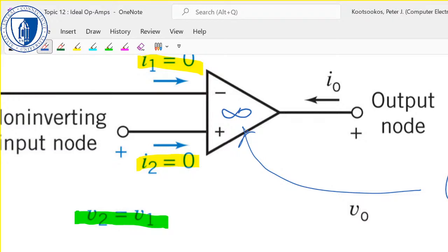As you change the frequency, at DC it's that level, at zero frequency. At a gigahertz, it's nowhere near that. It's maybe 1, maybe 2. You can get microwave level operational amplifiers, but they're very expensive. And there's better ways to do gain in that area.